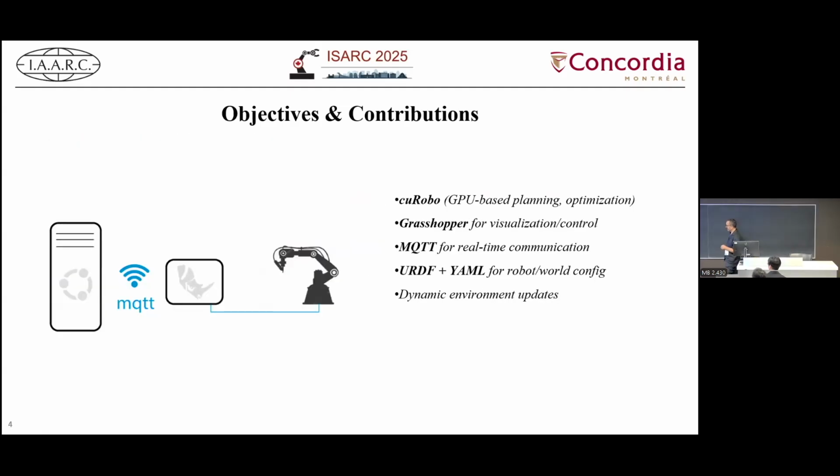So what we installed was a server, it's a Linux, a Debian computer, that is on our faculty somewhere in the rack, and it is running this cuRobo software, and it's getting, in fact, information from the user, from the client. And the client could be any computer that has Rhino, and the communication works over MQTT. MQTT is a very, very simple communication protocol in real time, but that's important.